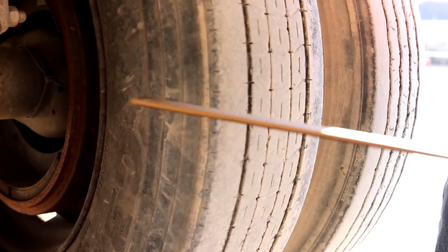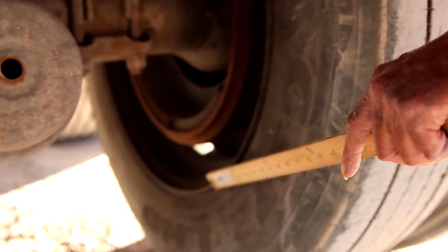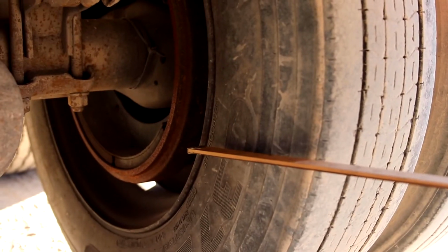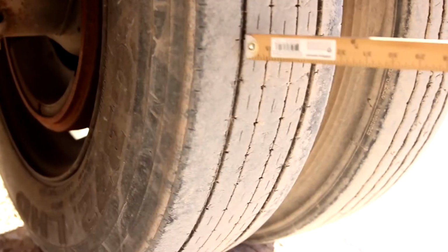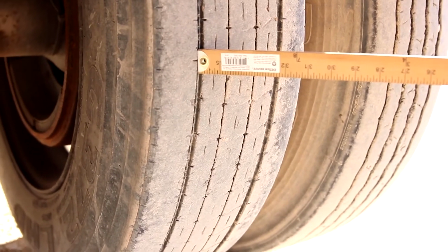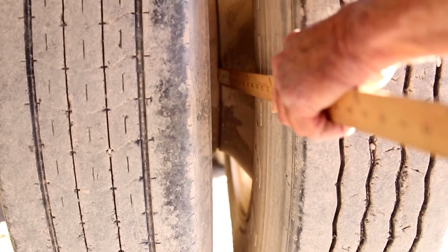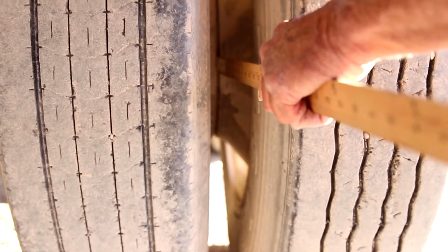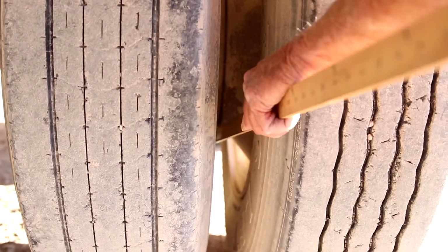Tires, again, you have dual tires back here, so check your inner and outer tire treads, or tire walls. Make sure they're mounted securely to the rims. No abrasion, bulges, and cuts. No audible leaks. Tread depth, again, must be 2/32 of an inch in each major groove, evenly worn. Dual tires, you want to check for any gaps between the rims. No daylight, the rims are not cracked, and no debris or trash.